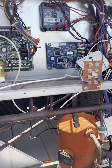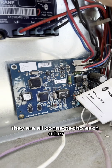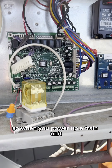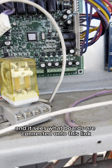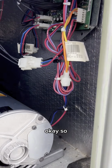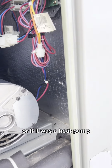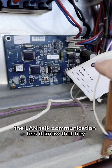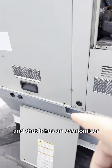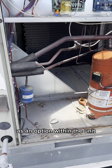When they are all plugged in, they are all plugged into this IMC link, or intermodule communication. It's basically Modbus. They are all connected to each other. The twisted pair, power, ground, and then the communication. So when you power up a Trane unit, the RTRM does like a whois command, and it sees what boards are connected onto this link. They then report what they are, okay? So this RTOM will say that it has dehumidification function, or if it was a heat pump, the LAN Talk communication lets it know that, hey, this is on a BMS system, so look for incoming BMS commands, and that it has an economizer, that you have an economizer mode as an option within the unit.